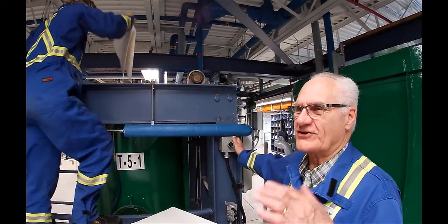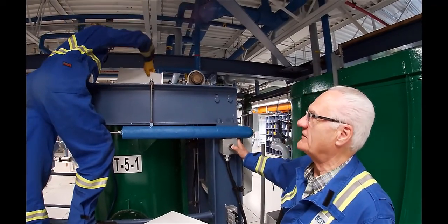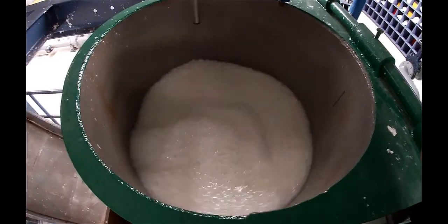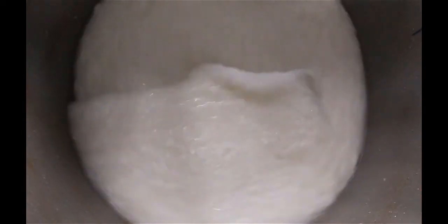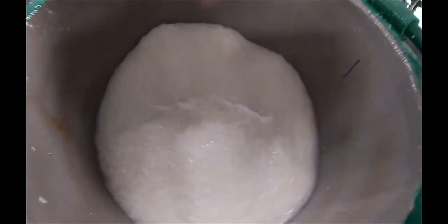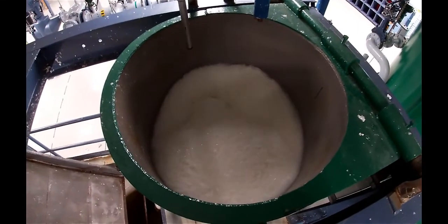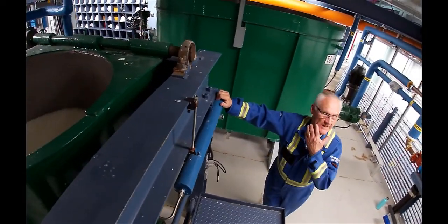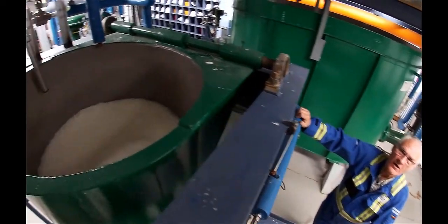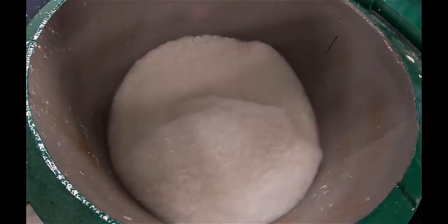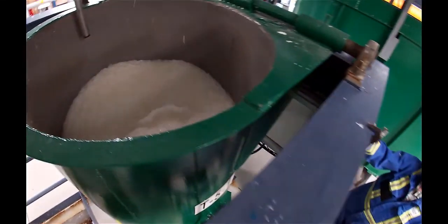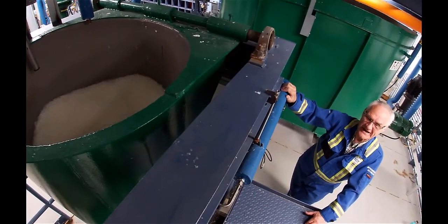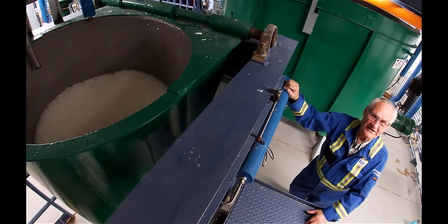I could hear that agitator slowing down a little bit because that stuff's starting to get thick, and now you see Mari's having to push those sheets in. Okay, so we've got half of the sheets in right now. Ray, just take a picture of what it looks like. And that's probably around 1.7, 1.8% consistency. It looks pretty thin. When we get the next 40 sheets in there, it's going to thicken up a lot.